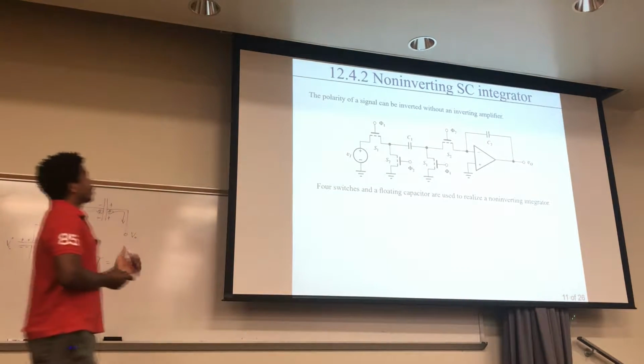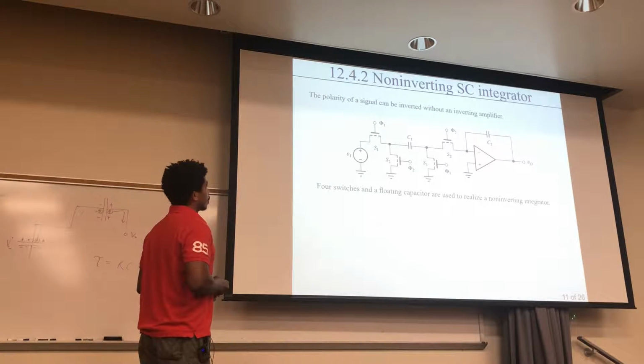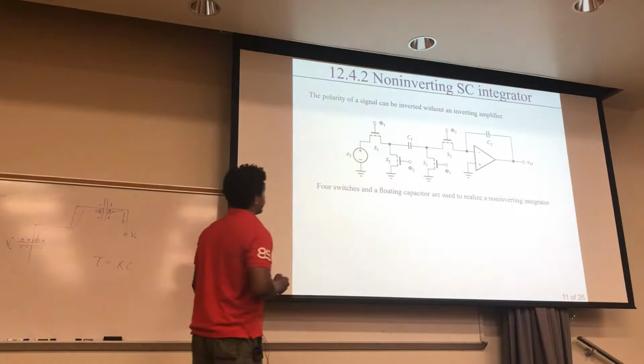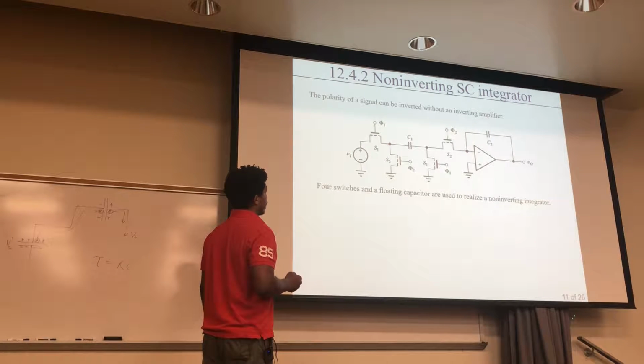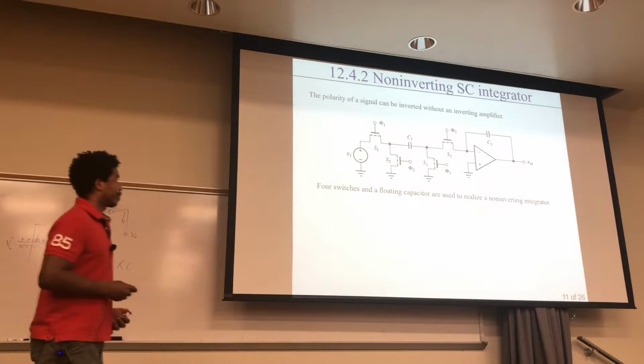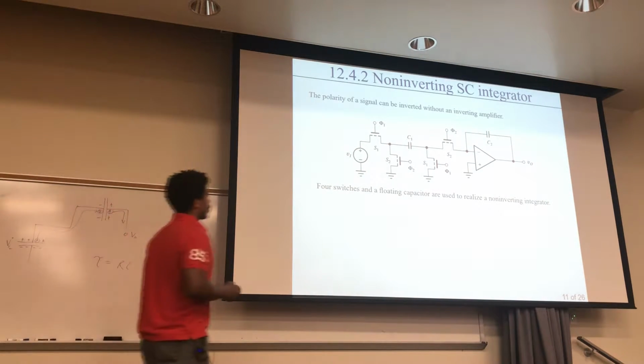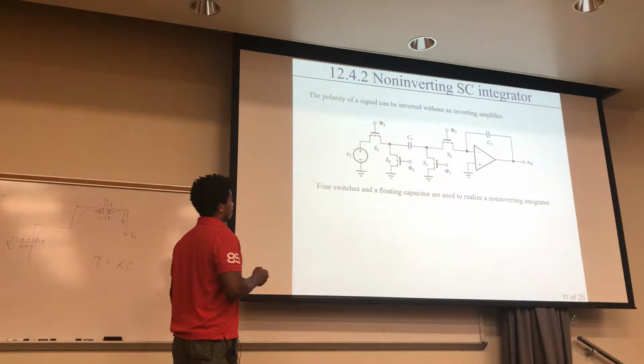All right, so let's look at non-inverting switch capacitors for integrators. So the polarity can be inverted without even using an inverting amplifier. And so let's go over that kind of scenario. In this scenario right here, you have 4 switches, and you have this floating capacitor right here. So you see this is S1, that's S1.